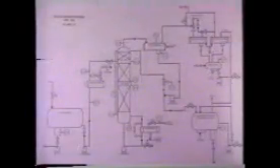He also regulates the flow of steam to the reboiler. This controls the boil-up rate, that is, the amount of vapors rising up the column. He uses a temperature controller to adjust the steam flow and control the boil-up rate. Both the reflux and the boil-up rate may need to be adjusted several times until the column temperatures are within specifications. At this point, we've reached the second stage of the startup procedure.